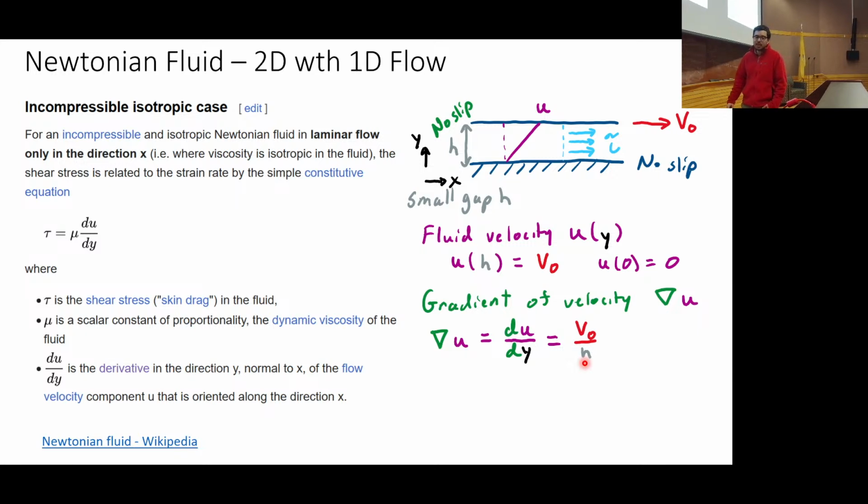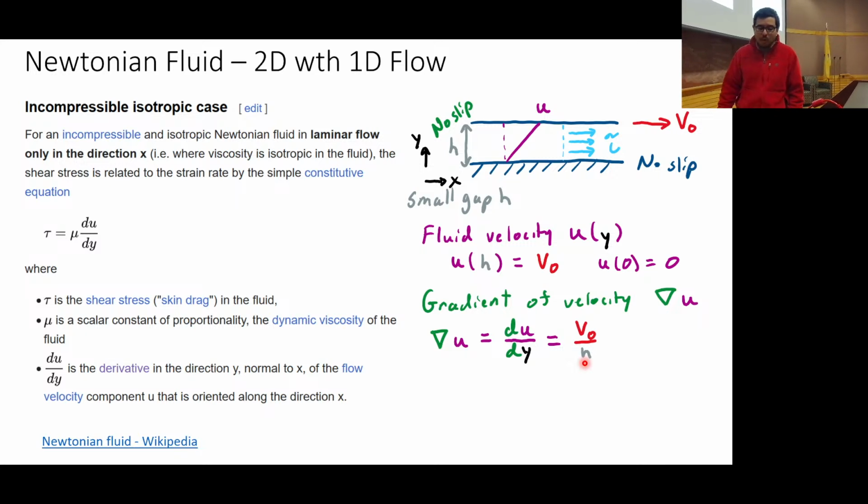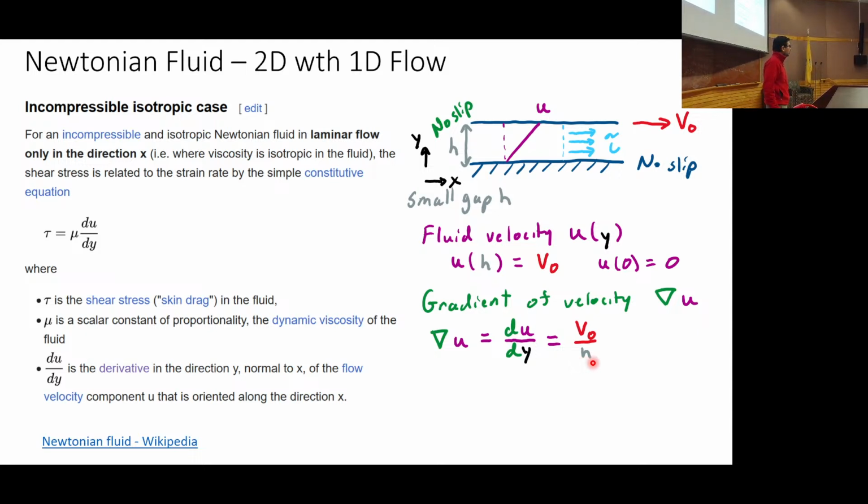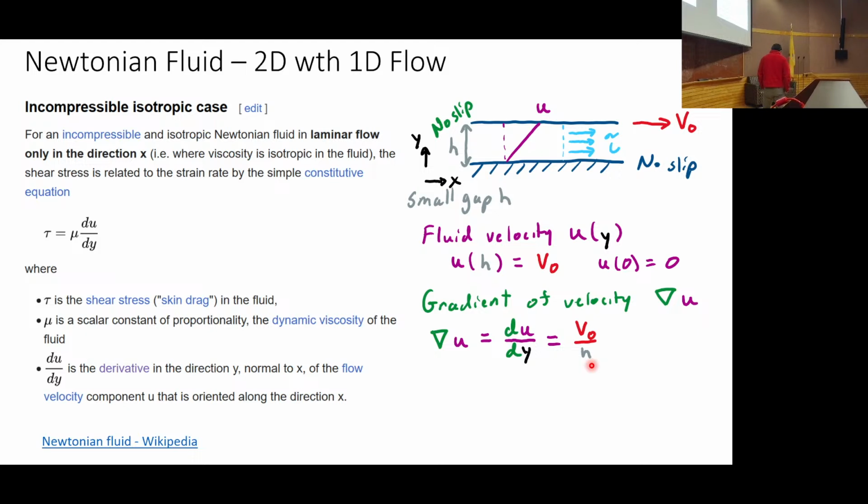So now let's go back to that question. What is a good way to measure the viscosity of a liquid? Or what is one way to do it? Yes, Rishi? Find the velocities at the top and the bottom so that you can look at the dy. And if you know the shear stress, then solve for viscosity. Okay, so how do I calculate shear stress?